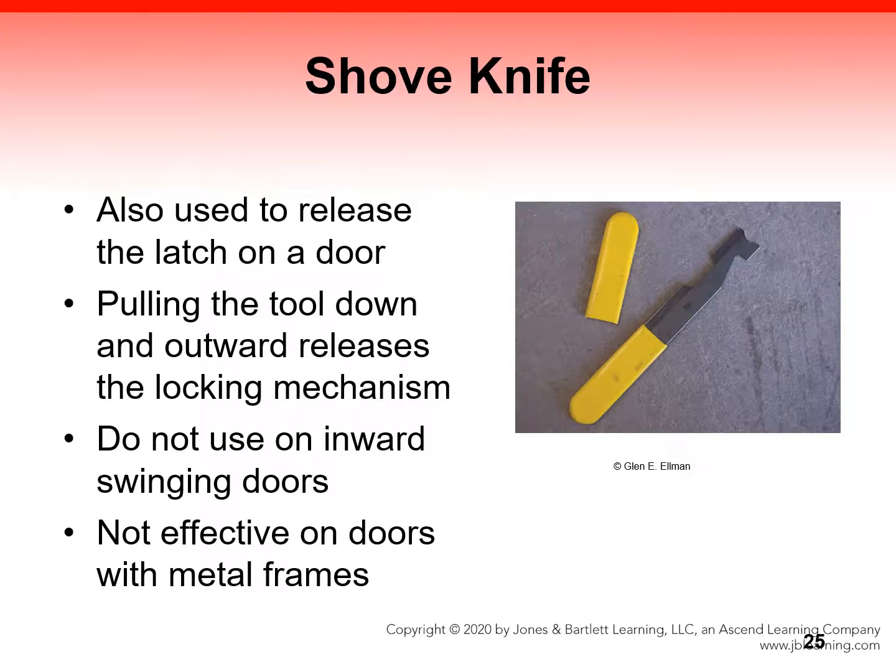A shove knife is also used to release the latch on a door. Pulling the tool down and outward releases the locking mechanism. Do not use on inward swinging doors. It's not effective on doors with metal frames.